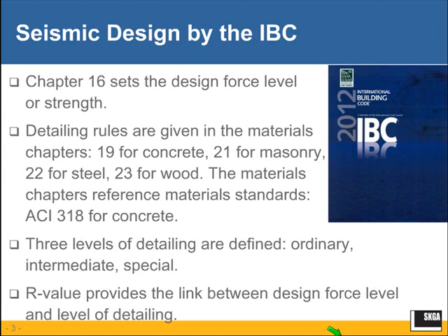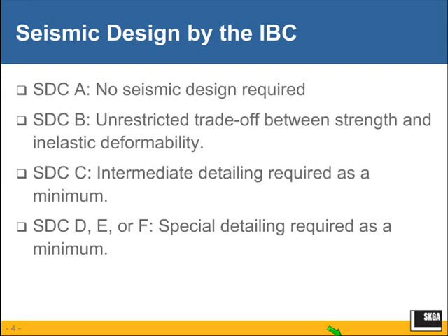The lower the R, the higher the design force level, and the lower the need for inelastic deformability or the need for careful or special detailing. Okay, so this is the overall setup.